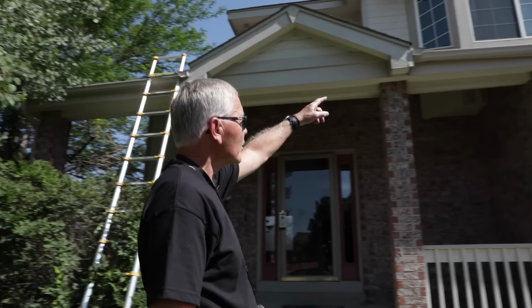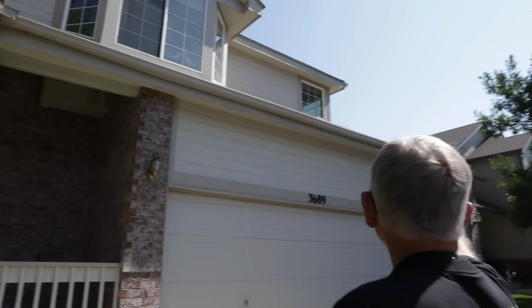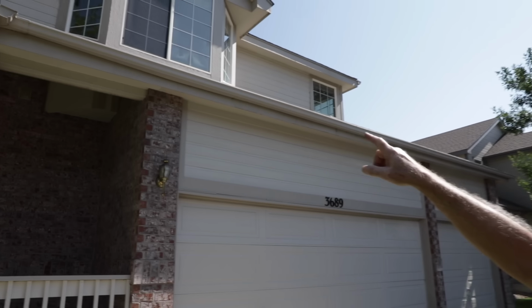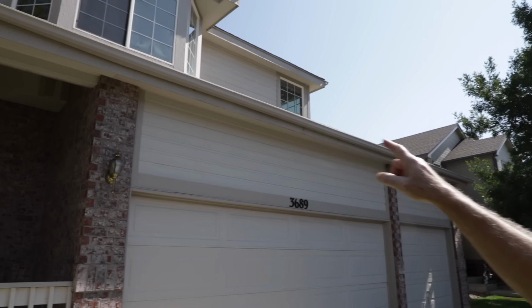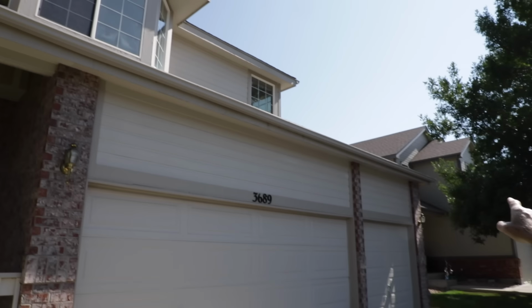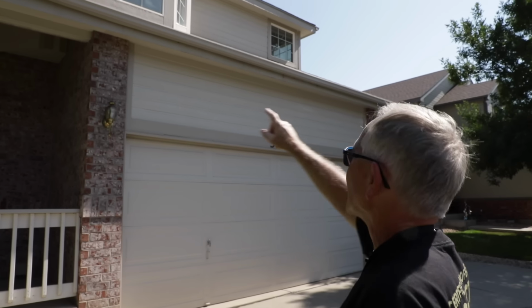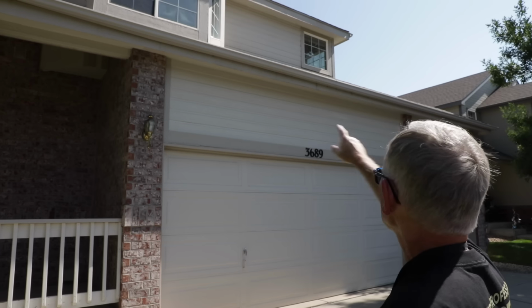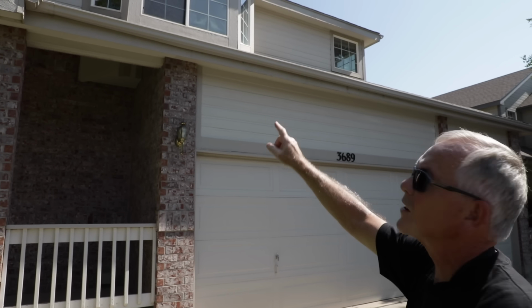Now we're going to inspect the gutters, and that is required in the SOP under the roofing section. The first thing I'm going to notice here, looking at this gutter on the front, I can see the slope is not what we'd like to see, about 1/4 of an inch per 10 feet. The middle looks like it's pretty low. So these gutters probably would not drain very well. So I'm going to recommend an elevation change in these gutters so they maintain that 1/4 inch per 10 feet.